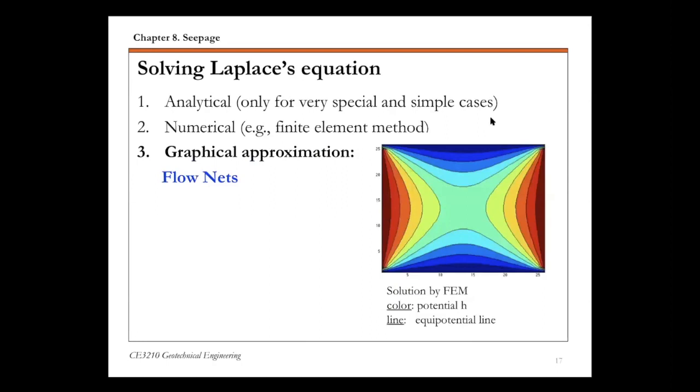And to solve the Laplace equation, there are three options. The first one is you can solve the Laplace equation using analytical solutions or analytical methods. But the analytical method only works for very special and very simple cases, like 1D flow through isotropic media. That's where you can get analytical solutions.